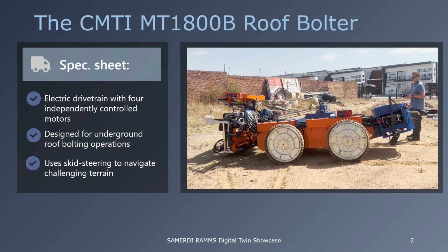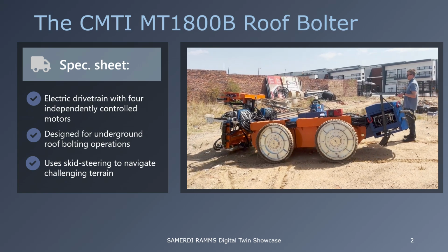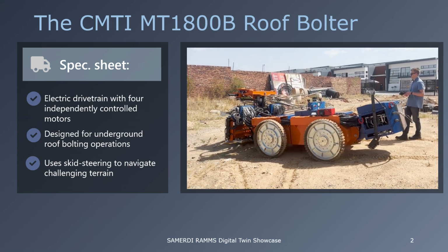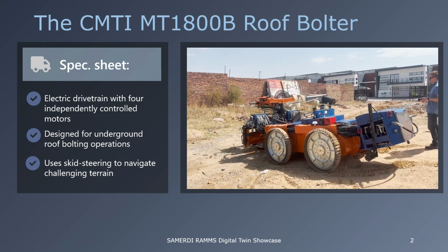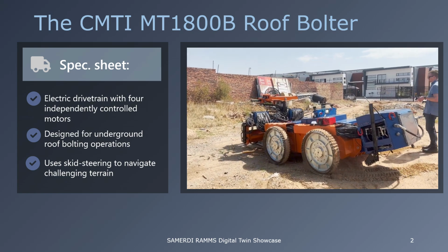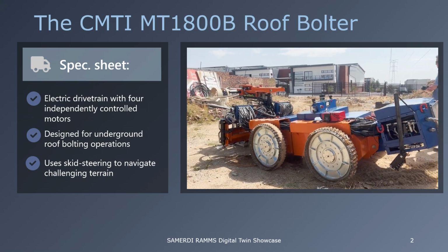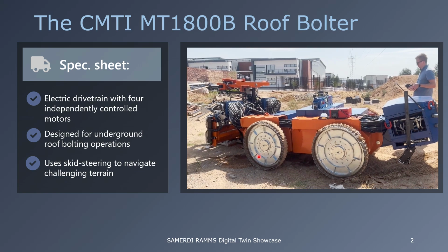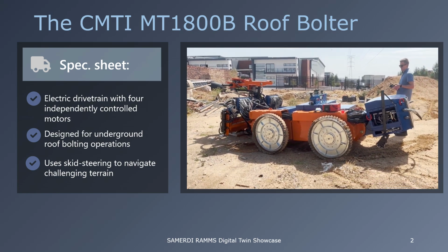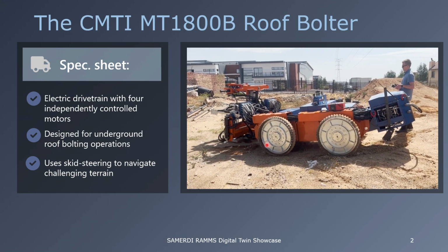This is the vehicle we're talking about. As you can see, it's skid steered. For those of you who don't know what that means, it means your wheels don't articulate to steer the vehicle. Instead, they rely on differences in rotation speeds of the different wheels to rotate. So perhaps, let me just grab a marker here. You'll see this wheel set was rotating in that direction while the other wheel set might be rotating in the opposite direction to get this thing to turn. So that is skid steered.